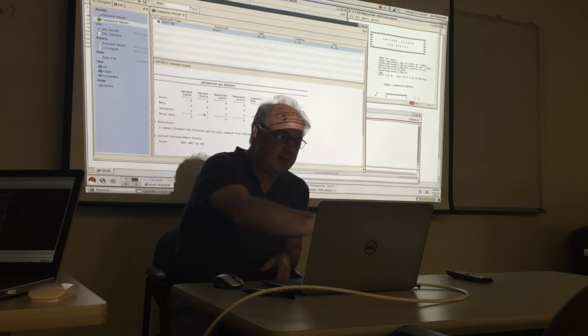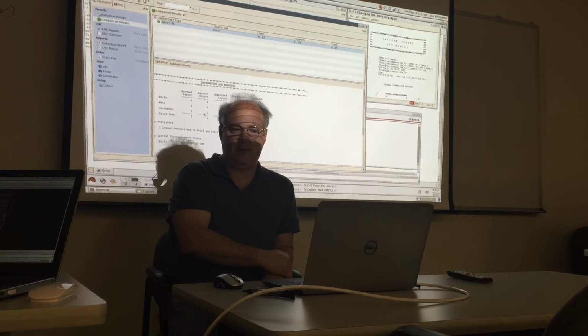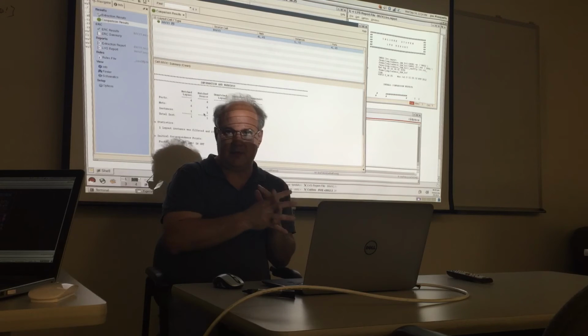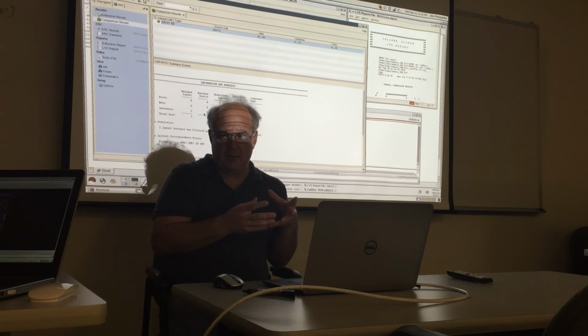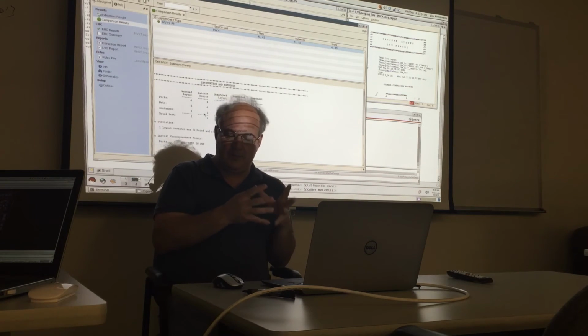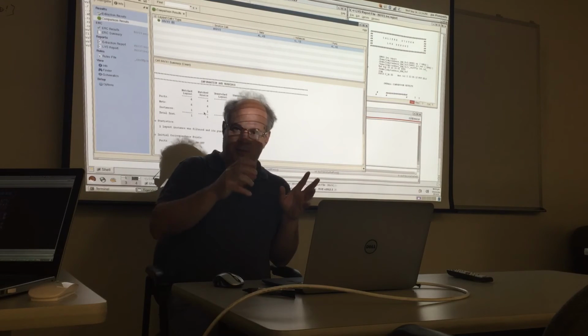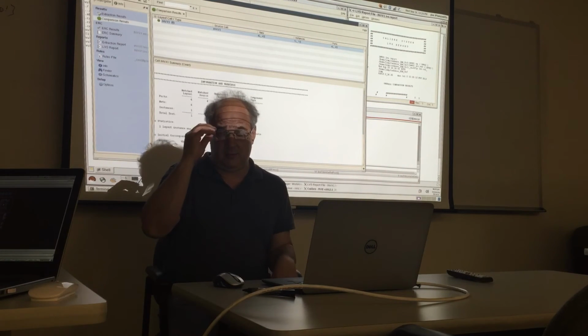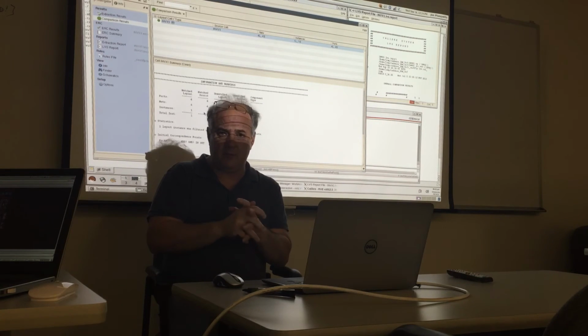It will give you more detail at the bottom here and it usually gives you pretty good clues on what's screwed up. It'll tell you what net is inconsistent between the layout and the schematic. I assume that you can design a schematic properly. Just be careful in your schematic, because you're really doing the schematic to make sure you do the layout right. If you don't do the schematic right, then you're really in trouble. So make sure your schematic is right. It's supposed to be a higher level abstraction that gives you a higher level view of the electrical connectivity and so on.